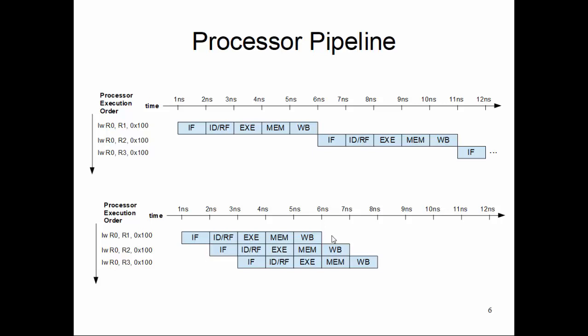So in the pipeline way, after the 5th clock cycle in this example, each clock cycle is the completion of another instruction, and so on. Let's say it's well balanced and all the instructions are executed in an overlapped manner. So I'm actually increasing the throughput, though the individual instruction's execution time remains constant.